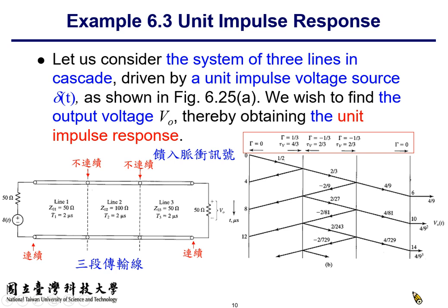So this is the so-called transient behavior. Okay, we know that there are signals bouncing back and forth in this transmission line system, but they only last for several tenths of a microsecond. So if the observation time is large enough, you can hardly tell anything is left on the transmission line system.